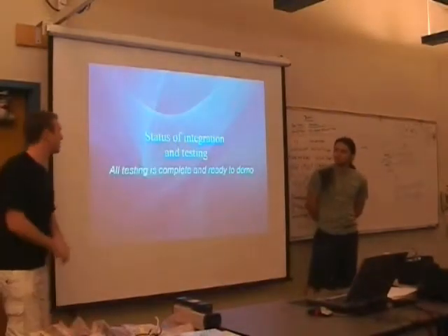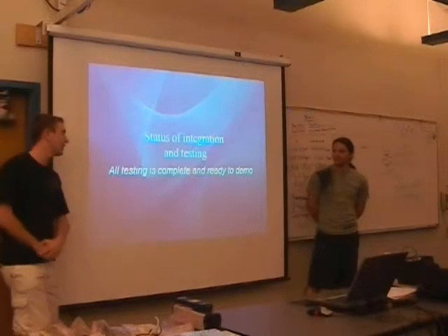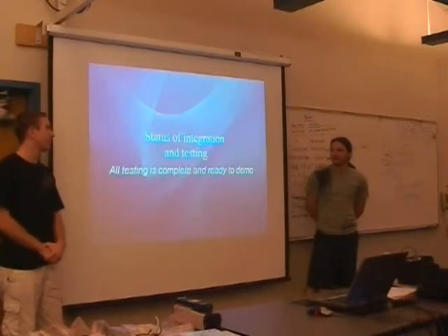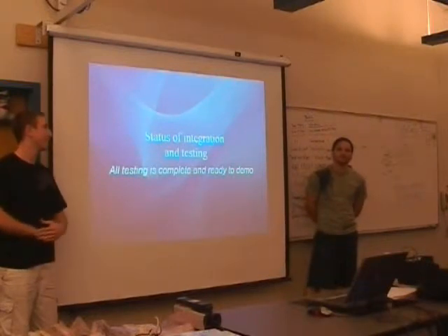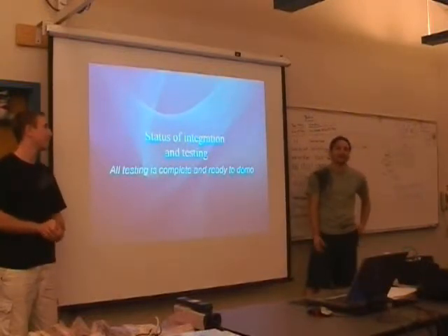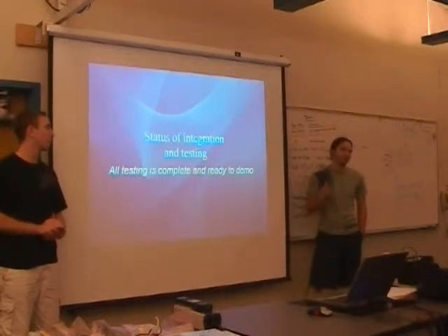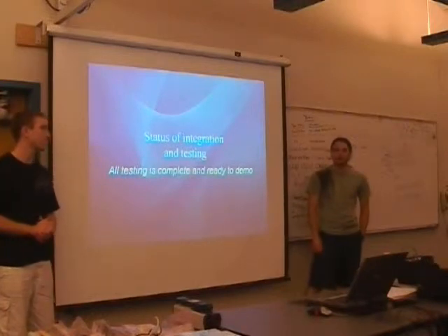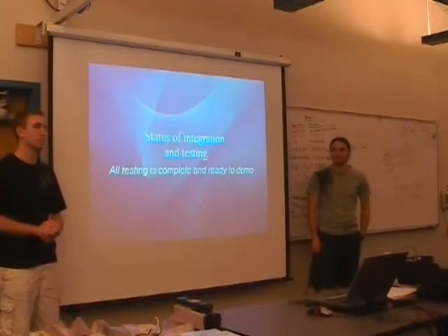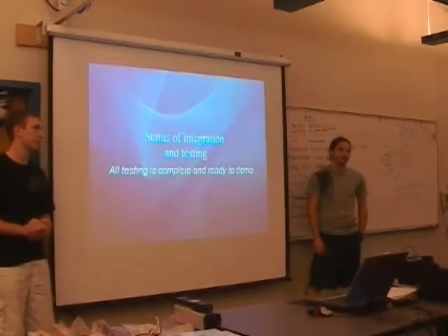And then we weren't really sure what this slide was supposed to be for, but we can sort of talk a little bit about the single LED. We did that the first week after our last lab. We got the pulse width modulation for just a red LED working, but one of the problems we ran into when we started using the RGB LEDs was that they're common anode instead of common cathode.